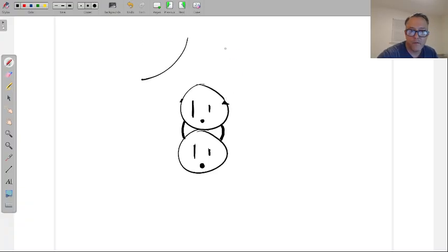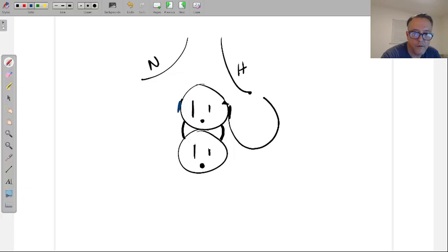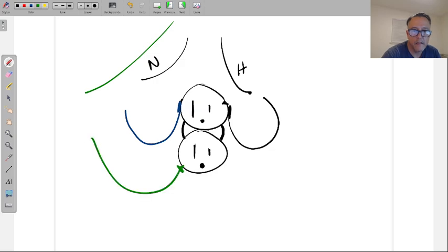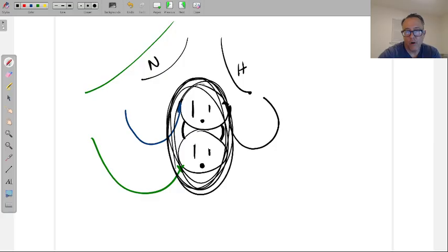All right, so now I got this wire over here and that wire over here. And so let's just say I put them in the right order. So now we have the hot on this side and the neutral on this side. So here's the trick. The trick is splice. Not a big deal, I didn't discover plutonium here. But you just land a wire on the hot, land your neutral on the neutral point. You have your ground as well, right? Land your ground. And now, don't do anything yet. Electrical tape around all of the screw points, making sure I can't see anybody.